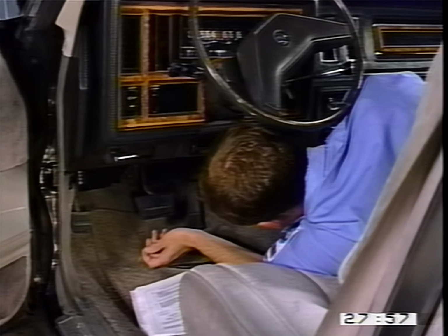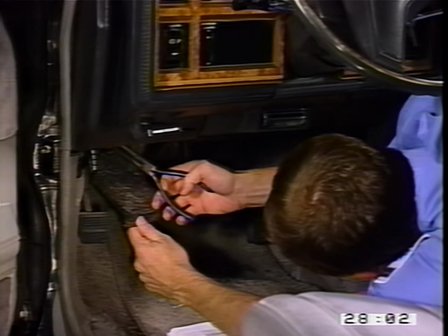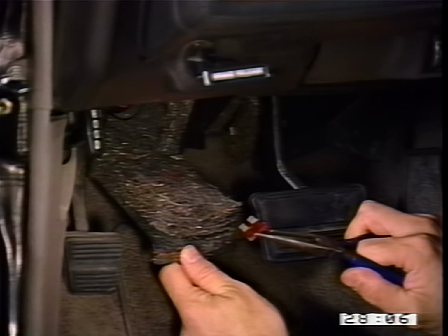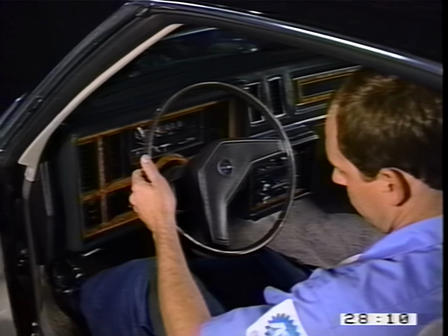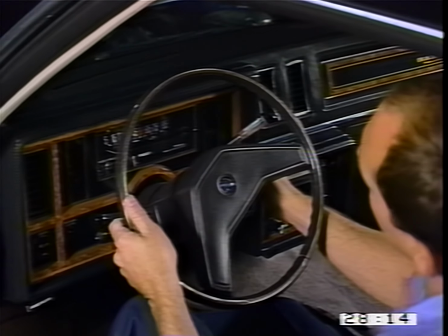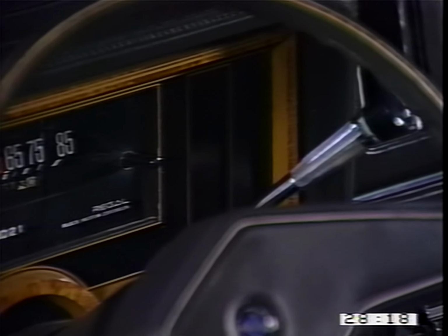Turn the ignition switch to off. Remove the ECM fuse from the fuse block for 10 seconds, then put it back. The trouble codes should now be cleared. Now that you have a list of the codes, apply the parking brake and put the transmission in neutral or park. Block the wheels and then start the engine. The service engine soon light should go out. Let the warm engine run for 2 minutes and check the service engine soon light.